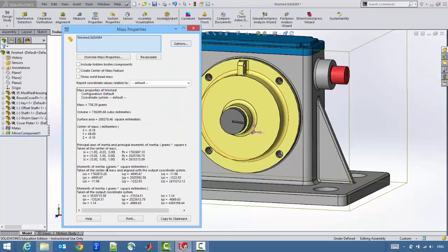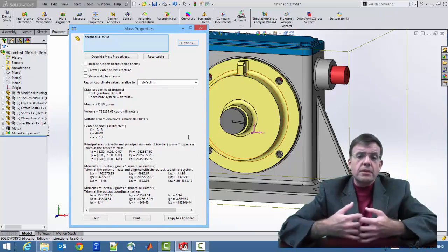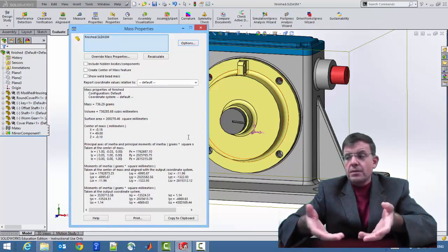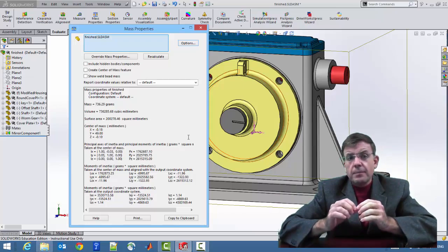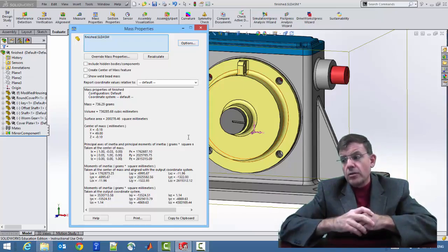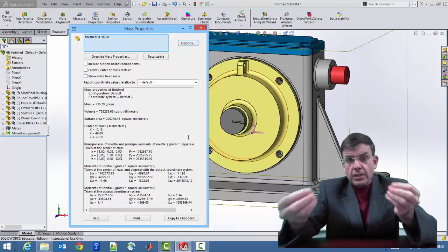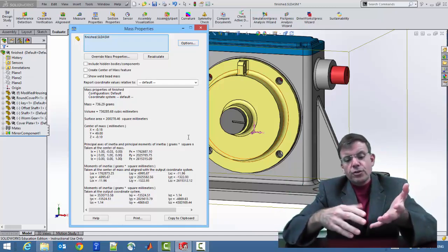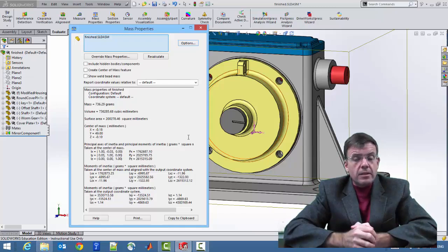Okay. So again, we won't look into them, but I would suggest, perhaps as an exercise, to take, say for instance, a simple geometry such as a box or a cylinder created in SolidWorks, assign a particular material to it, or even without the material assignment, you would get an adequate result, and find out what the value of a particular moment of inertia is around a certain axis, and then compare it with tabulated values that are, again, for simple geometries, so cylinders, spheres, cones, boxes, in the appendix in your dynamics book.